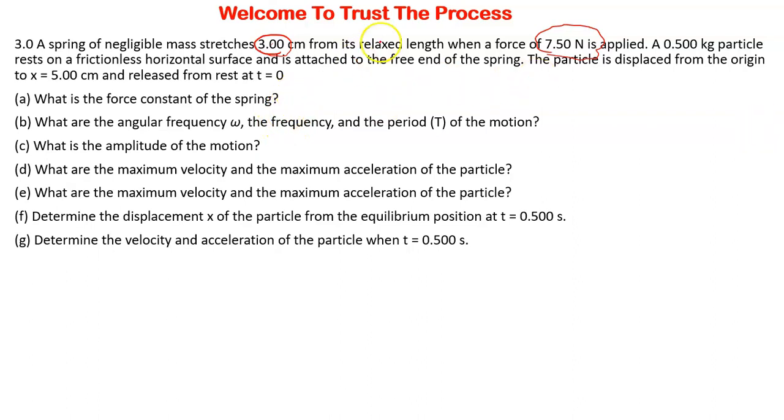What you have to know is the stiffness of the spring can never be negative, and hence when finding it, you are going to say the magnitude of the restoring force is given by F = kx, where we know that k will just be equal to the force over that extension. In the question, the force of 7.5 is the one that caused the extension of 0.03 meters.